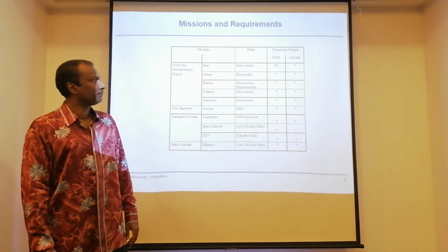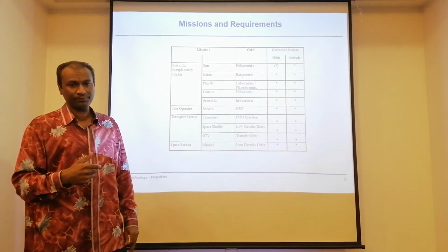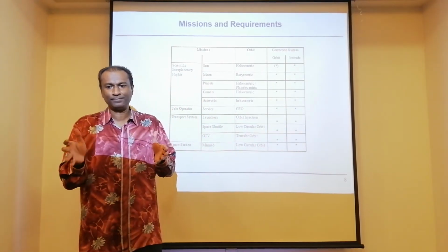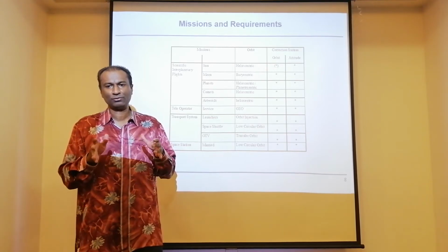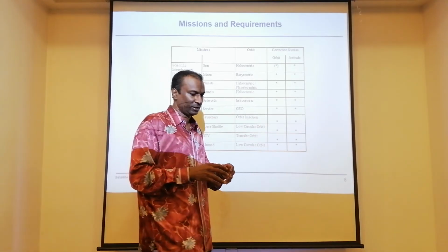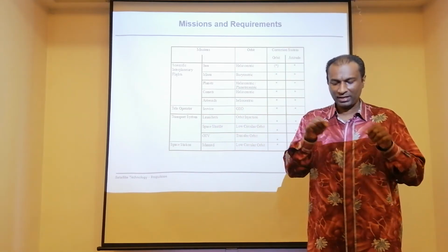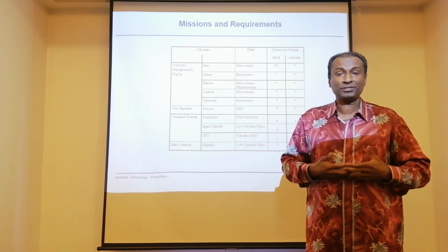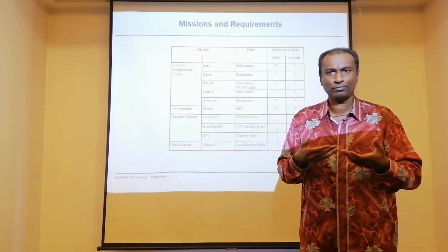Now if you look at it, that means the orbit system, or the orbit motion, is optional. But the attitude motion, the rotational motion, in any satellite is a must. That means you should have the attitude control system in a satellite. It is mandatory for any satellite. It could be low cost, etc. Rotational motion is mandatory. Translation motion, when it is operating in its orbit, is optional. If you embark a propulsion system on the satellite, it is going to cost you more.